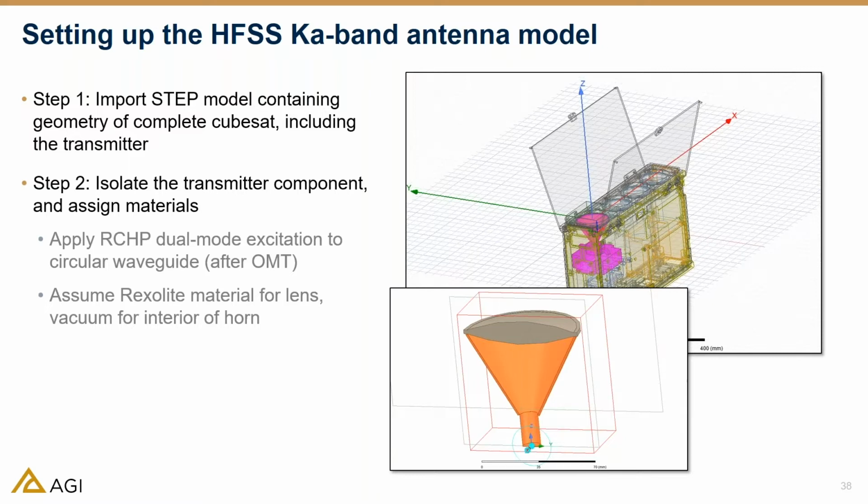Now the lens also has, and you can see the cross section there in that grayish area, some shape approximations that appear to be facet-like that are probably an artifact of the simplification of the CAD model for model export. And this is likely to affect somewhat the model's prediction of beam focus and probably side lobe level control.